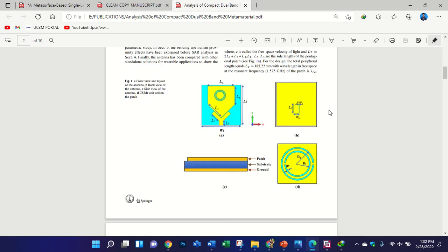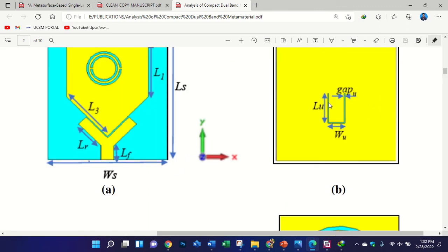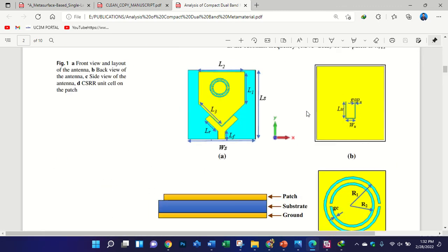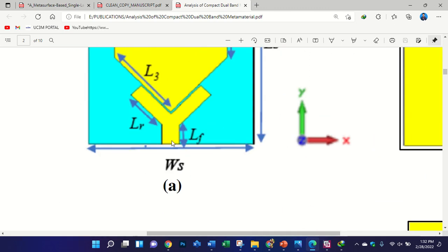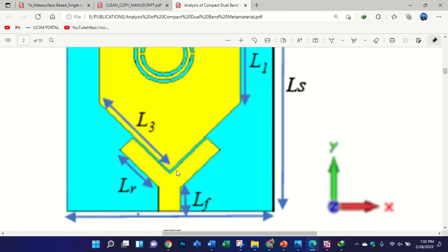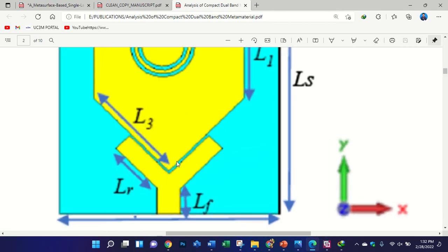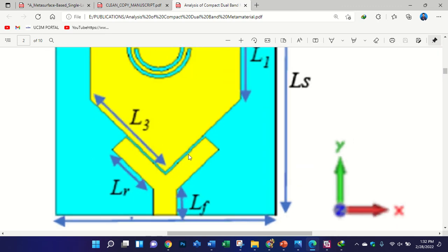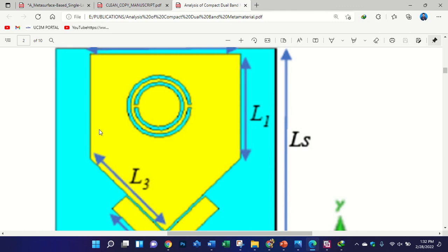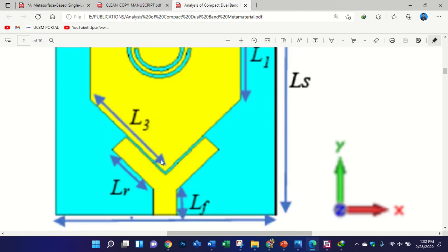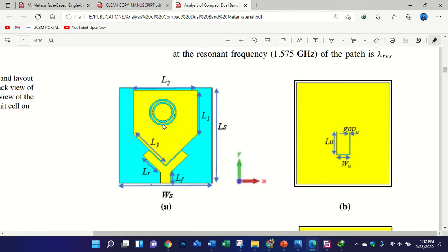And there is a full ground plane, just a U-shaped slot inside the ground plane. Mr. Ahmed, for this image, how is the antenna fed? Waveguide port, okay, with waveguide port here and the feed line. It is not touching, but it is very near, about a 0.2 millimeter gap. So in this way you can see the surface current is also flowing on the other patch, because this is a part of one layer, not other layers.